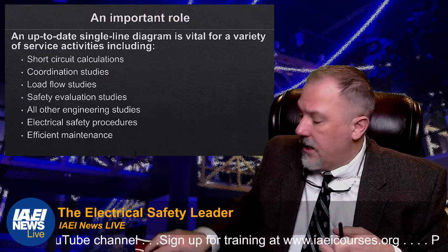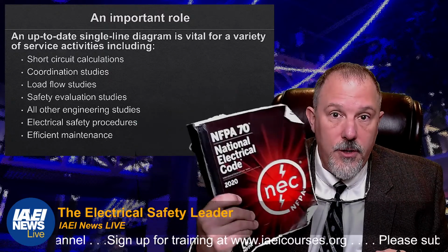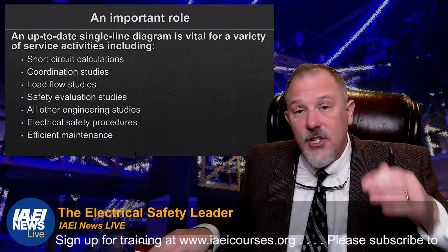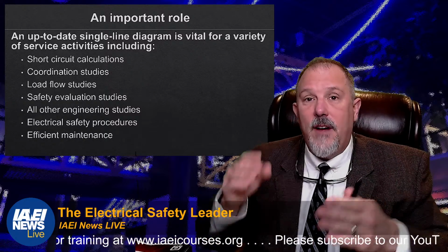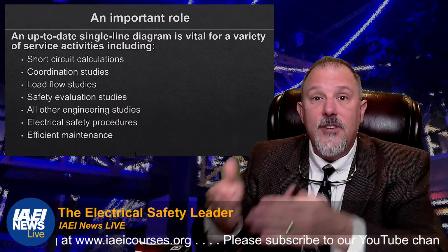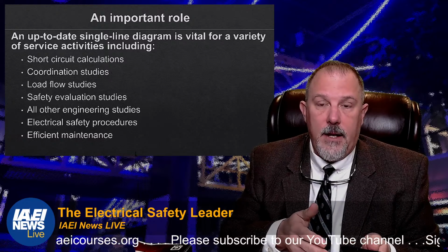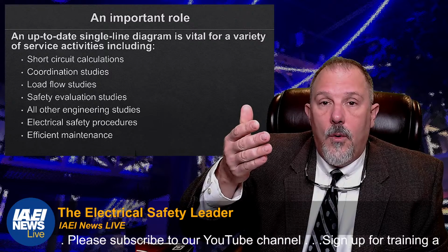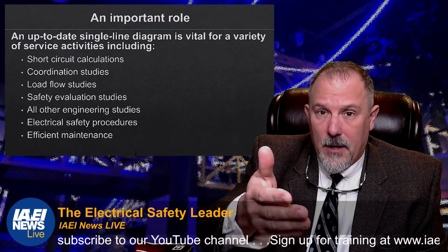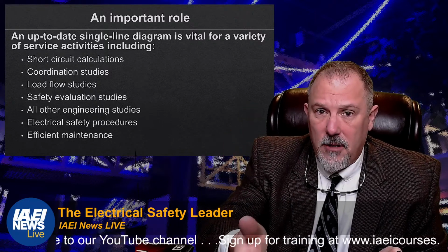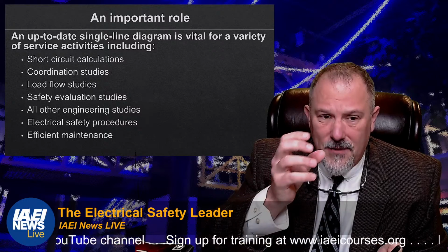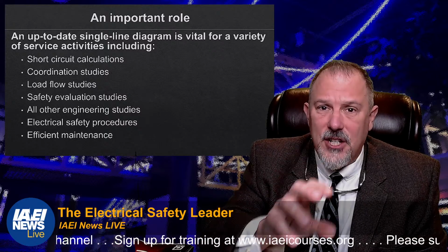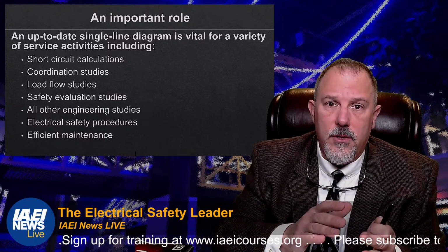We're going to talk about the National Electrical Code, which has provisions that say you have to lock and you have to have provisions for a lock in certain applications. And it gives us rules with regard to the lockout mechanism having to remain with the circuit breaker, right?